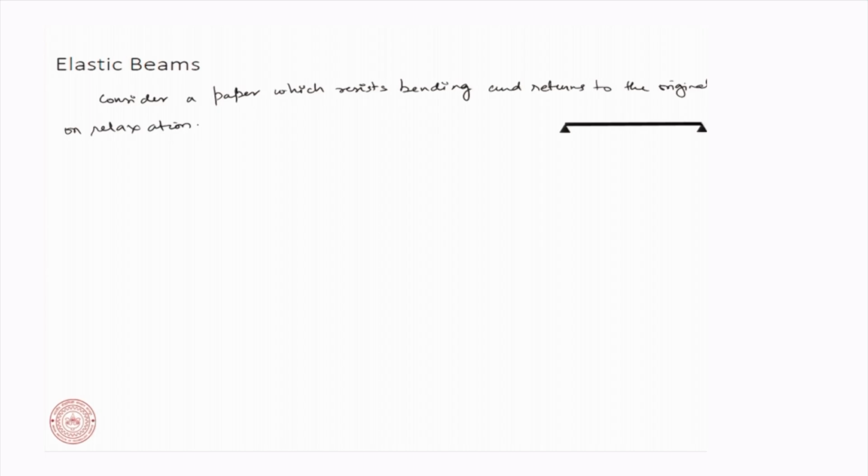Okay. So, this is a beam, it has a considerable thickness delta z compared to its length, that is L, in the x direction, Lx. So, delta z is not negligible when you compare it to L. If that is the case, then again from our energy equation, the total energy was a summation of our elastic energy and then some body force energy. As of now, we ignore the body force energy. We will come back to it, or we will add those terms later. If you just look at the elastic energy, there is no gravitational effect.